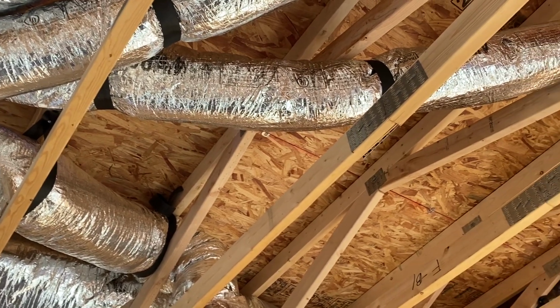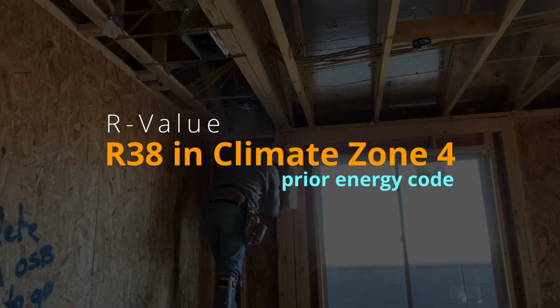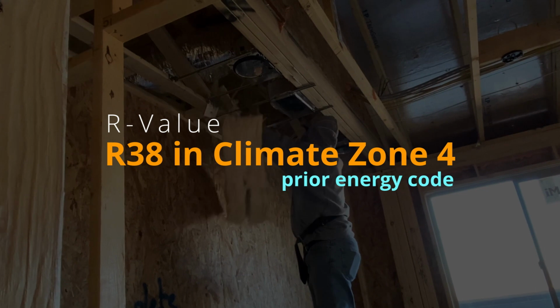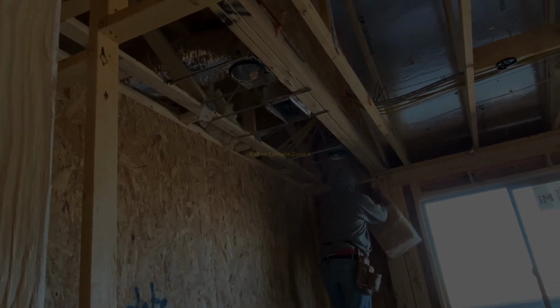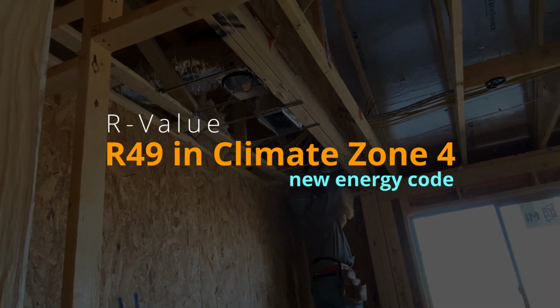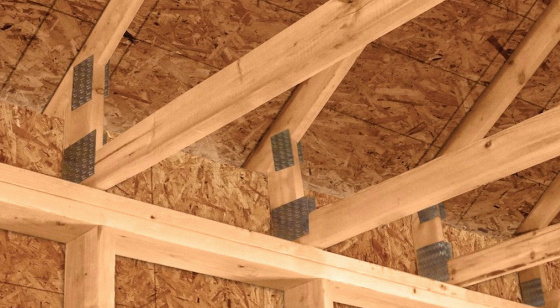R values in ceilings are bumped up too. In Climate Zone 4, for instance, buildings were required to have R38 in ceilings under the prior energy code. They will be required to have R49 under the new code. That's a pretty big jump. But here's another tip. Use raised heel trusses.